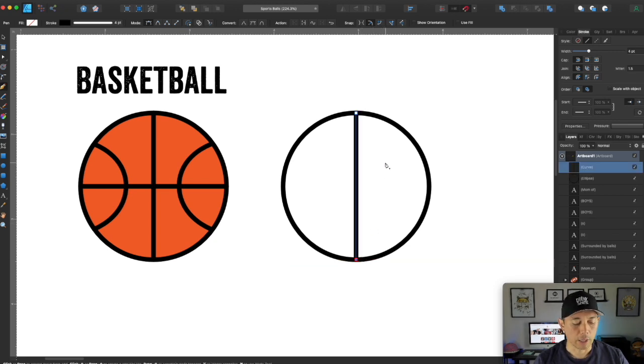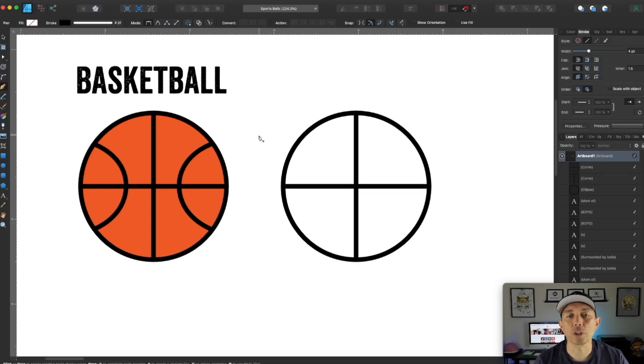And the next thing you want to do is hold down Command, and you can see it turns into the node tool. So click anywhere with the command, and that's going to release you from or stop you from connecting this line that you just made. So now you still have the pen tool here. Click on the right center, you can see right there, hold down Shift, click on the left center, and now you have those 2 lines. Hold down the Command key and then click anywhere outside, and you can see that stops it as well. So we're gonna do 2 more.